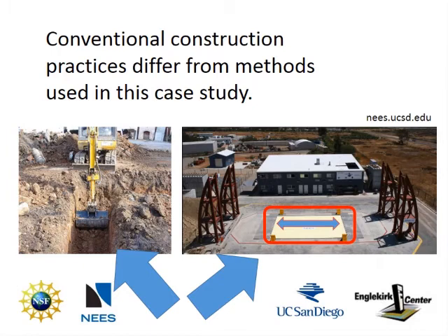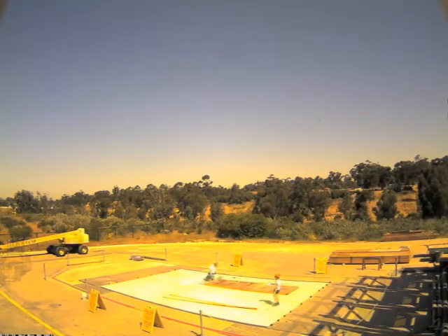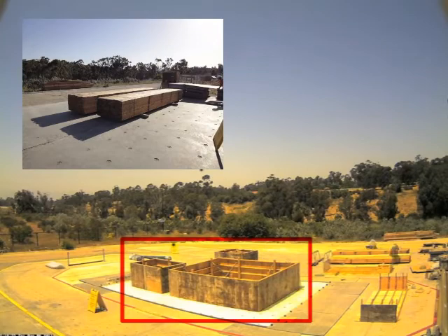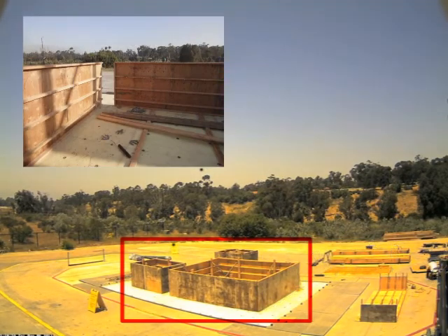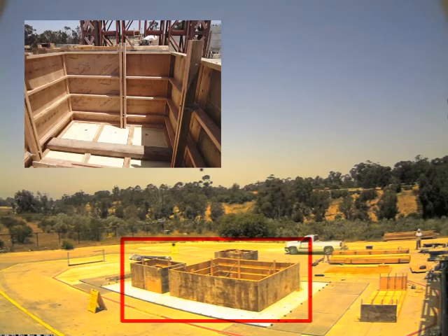In the field, however, shallow footings can make use of the natural side walls provided via the excavated earth, but formwork in the field is required if the side wall of the foundation extends above the natural grade or ground level. Depending on the design of the foundation, the formwork may often require both an interior and exterior segment to support the structure of foundation components.